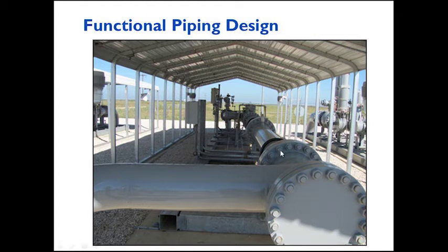And for that reason, it's good to install some inspection tees so that periodically you can shut in and examine that tube to see if it is getting dirty and how dirty it is in particular. But these tees have caused us some problems integrating the meter tube into the rest of the piping, and we'll be talking about some of that here in just a moment.